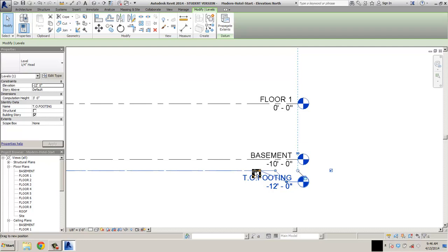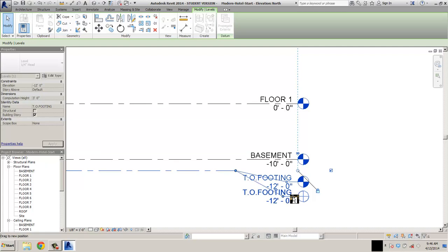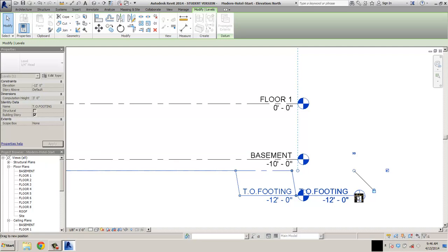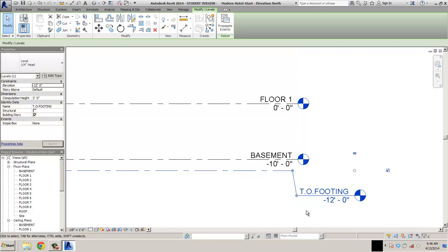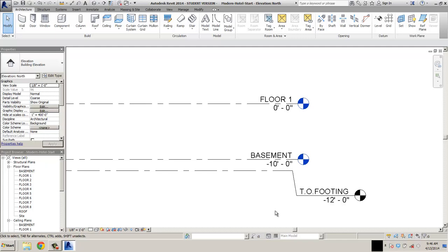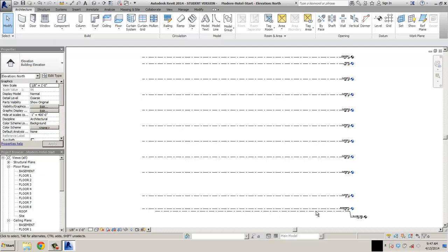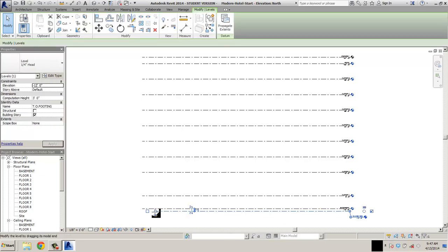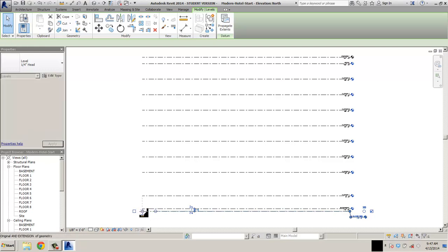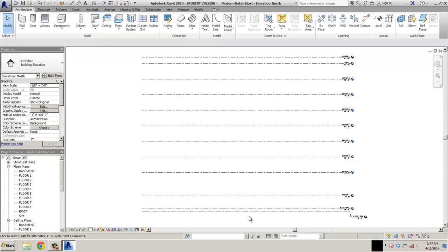So I can pull this line over. These little handles I can now use to create kind of an elbow on this whole system and pull those things out so that we don't have text that's kind of interfering. So again, it's black, so there's no floor plan associated with it. I'll do a ZE for zoom enter. There's our entire piece. See if I can pull this out. Oops. There you go. You see how it lines up with the other ones now.